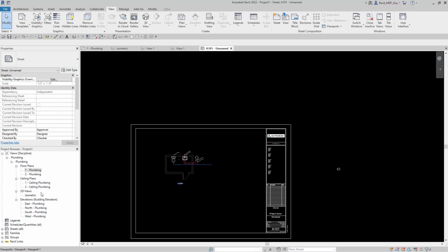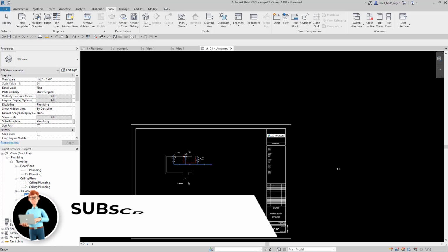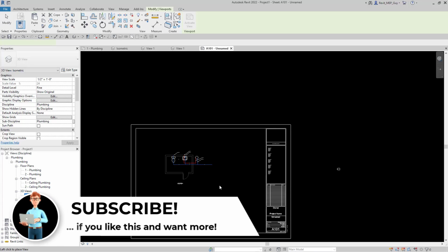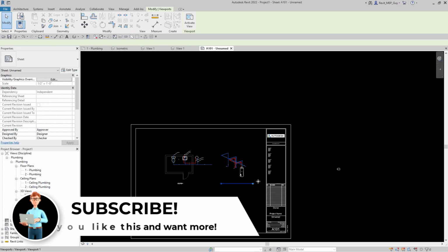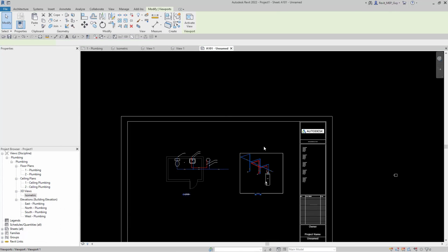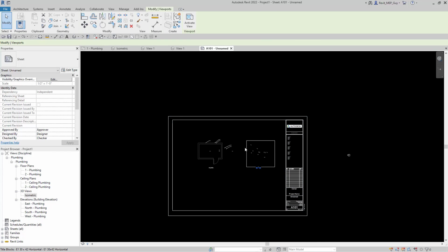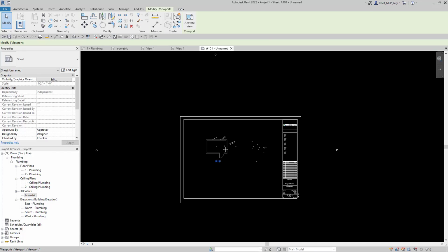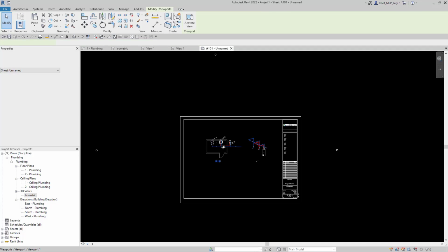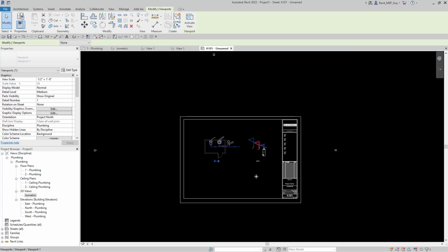And then let's bring in our isometric drawing. So if we go up to 3D, drag it in. And we'll put it right next to this view. Select this view. We'll deactivate this view. Oh, it's already deactivated. And now that I'm zoomed out, I can select these and use my arrow keys.